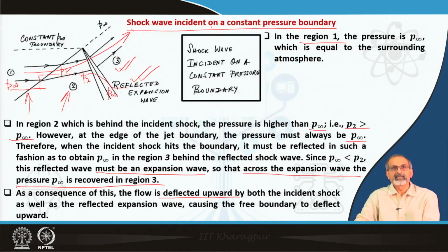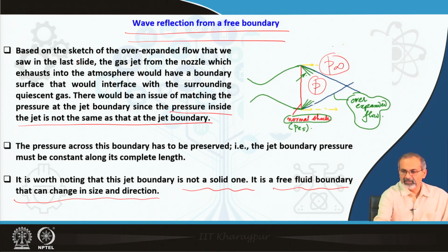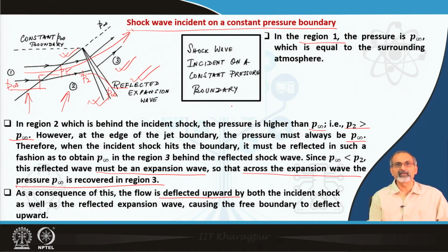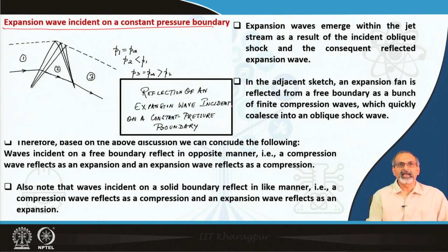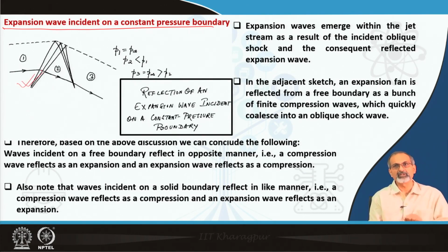We have to realize that in the earlier figure, if you have an incident shock which might have come from a situation like this, later on it reflects back as an expansion wave, and then what would happen is that this expansion wave will cross the center line of the jet and move over to the other side, while the expansion fan which forms from the lower side comes back to the upper side, and we are having a look at such an expansion fan here which has come to the upper side.